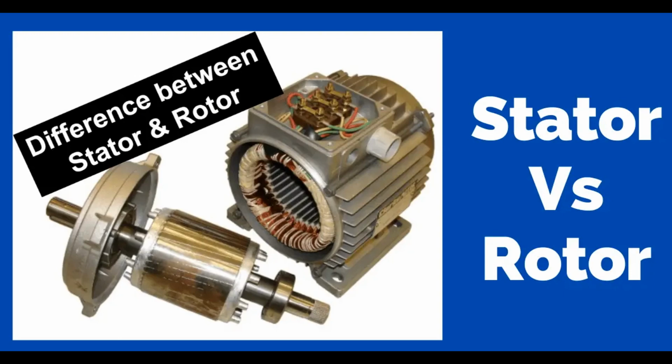The stator of an alternator generates alternating current, AC, due to the changing magnetic field induced by the rotating rotor. This AC output consists of sinusoidal waves that change direction periodically. Need for DC. Many electrical devices, including the majority of vehicle systems and batteries, require direct current, DC, to function. Since the AC output of the alternator is not suitable for these applications, it needs to be converted into DC.